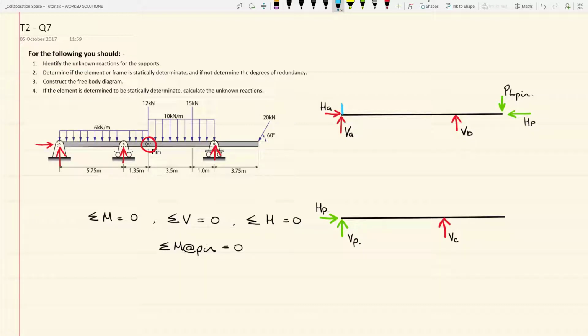So firstly, on part A of the beam we have a UD load. We also have a UD load to part B of the beam. In addition to the two UD loads, we have a point load, again acting at the pin. Note, we will only apply that once. Now you can apply that to either part of the beam, it doesn't make any difference, but you only apply it once. So I'm going to apply it to the end of the cantilever.